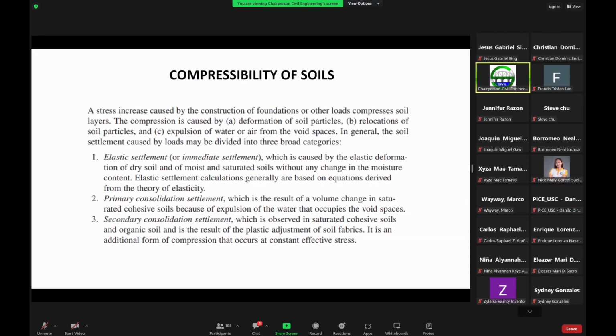That's already about half a meter, because the structure is not so sensitive with respect to settlement. The only concern is with respect to the cables, no? The transmission cables, which can tolerate as deep as 500 millimeters of settlement. So it depends on the structure that you're dealing with.